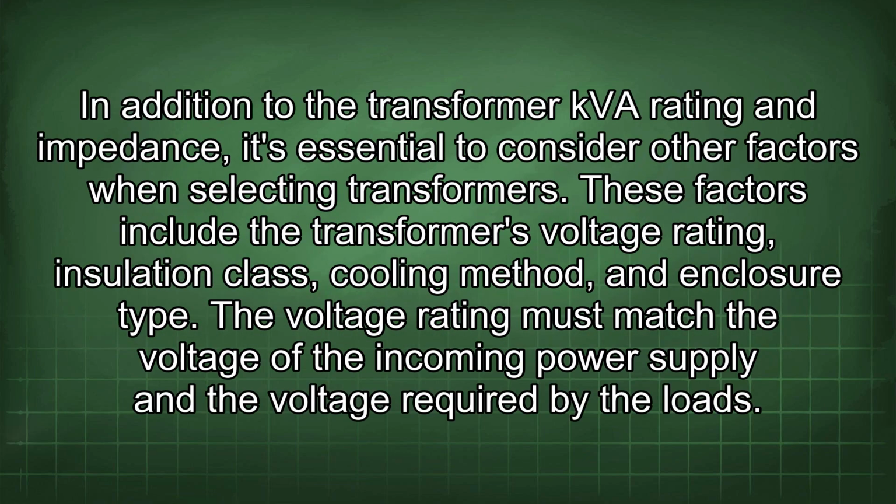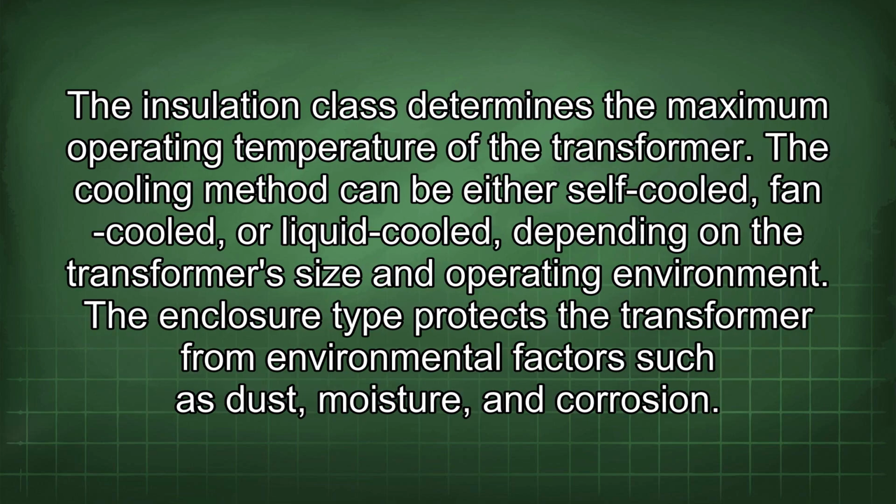In addition to the transformer kVA rating and impedance, it's essential to consider other factors when selecting transformers. These factors include the transformer's voltage rating, insulation class, cooling method, and enclosure type. The voltage rating must match the voltage of the incoming power supply and the voltage required by the loads. The insulation class determines the maximum operating temperature of the transformer. The cooling method can be either self-cooled, fan-cooled, or liquid-cooled, depending on the transformer size and operating environment. The enclosure type protects the transformer from environmental factors such as dust, moisture, and corrosion.